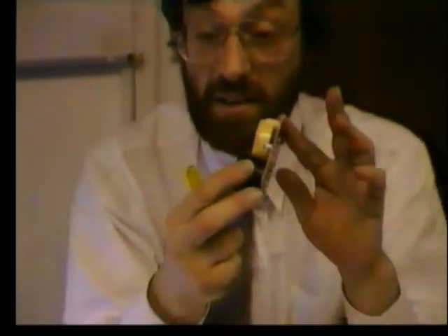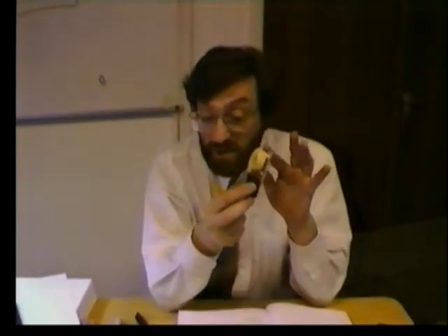That's how they work. Very, very low radioactive layer. But as soon as the particle gets in there, it's ionized and a current will flow between the various electrodes, and thus we have the simple domestic smoke alarm. But again, it's a transducer because it is converting particle size into electrical current.